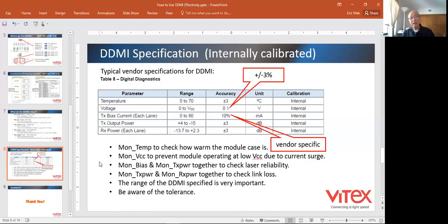Okay. That, I use it all the time when I see a switch is fully populated, because most of the time the VCC drops. Okay, when it drops to a certain level, plus or minus 5%, it will violate the operating condition on 3.3 volts.